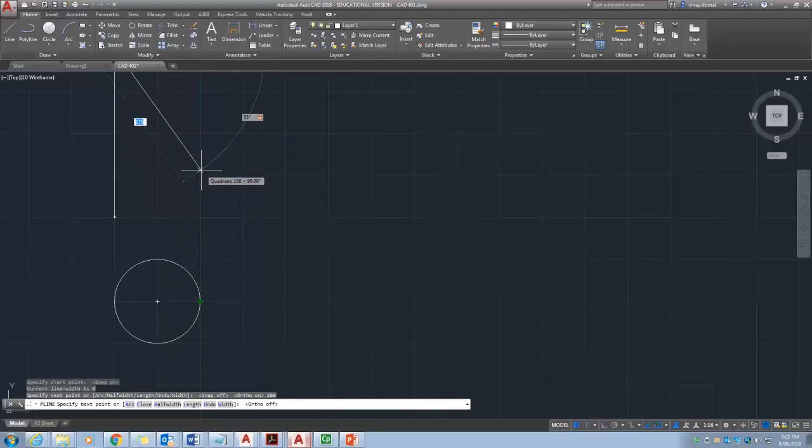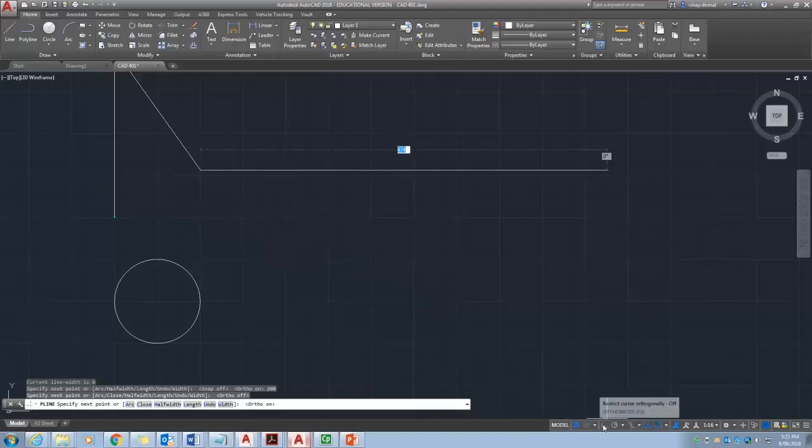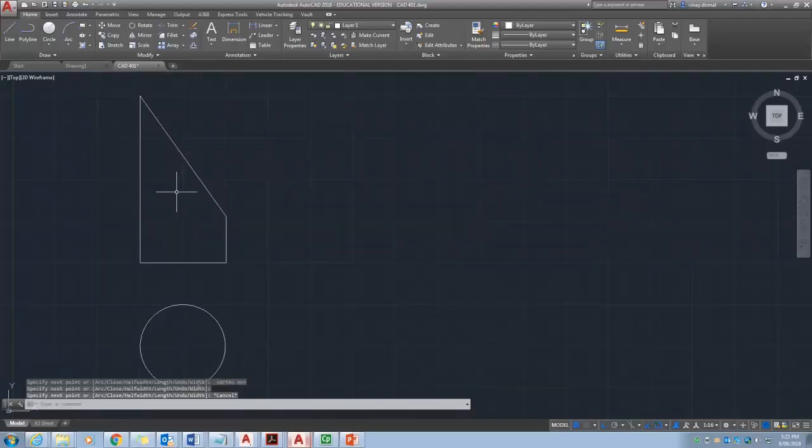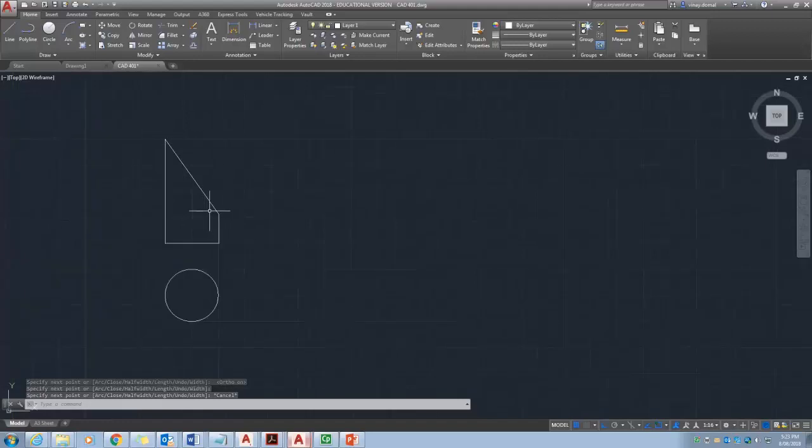So you can snap now. As you're moving, you can see the inference there. So that should be fine. Snap there. Again, find the inference horizontal line, and that way you lock the vertical line. If something is happening that is not going in a straight line, just activate the ortho. Again, go and find the inference. It will lock you to the intersection. Lock it back here. So that completes the section of that particular tube.